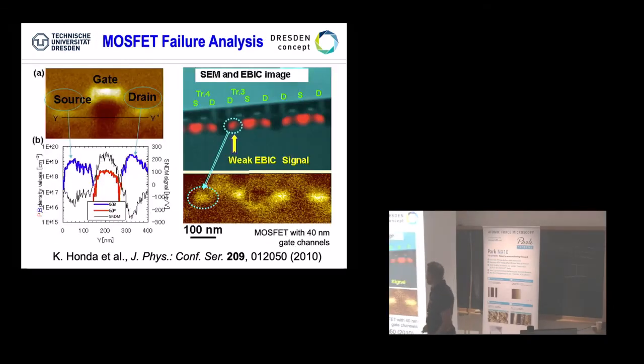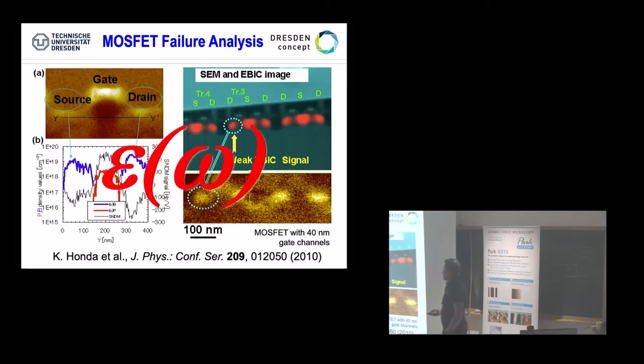Nevertheless, they applied this to some analysis. For instance, on a TEM analysis, they were looking at these kind of samples prepared by focused ion beam: source, drain, gate. And in fact, yes, they can fit the boron and the phosphorus doped areas exactly to this really 90 nanometer gate area. So that's one of the big challenges to go for industry with that. So the value they got is this epsilon of omega. It's only the isotropic value. You can get, as I was saying before, the anisotropies of the system, but you get it definitely at this frequency omega, which is microwave.